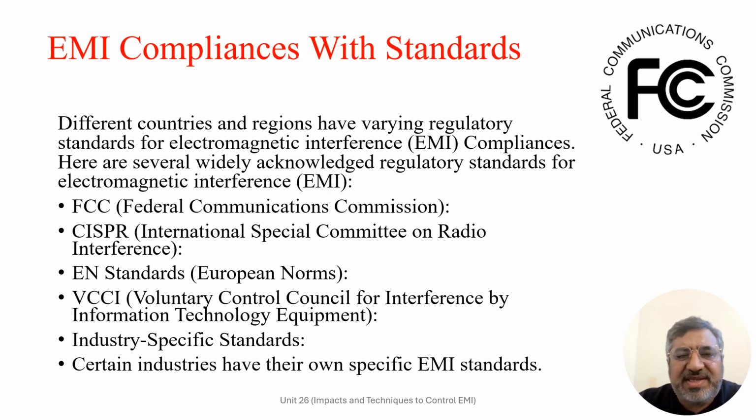The FCC in the United States sets standards and regulations for EMI under Title 47 of the Code of Federal Regulations, CFR. The FCC regulates both intentional radiators, devices that intentionally transmit radio frequency, as well as unintentional radiators. Unintentional radiators are devices that may emit unintentional radio frequency energy. It defines limits for conducted and radiated emissions for various frequency bands and equipment types.